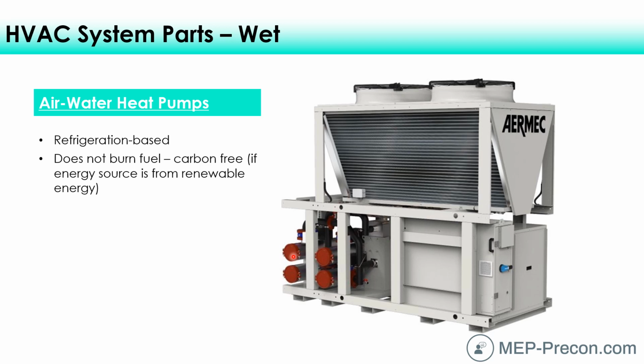So that's a pretty efficient way to get heating hot water, as long as the ambient temperatures are in the proper range. If it gets too cold, these don't operate. And that's kind of intuitive, because if the ambient air is pretty cold, there's just not a lot of heat to be able to pull from to pump into your system. If it's warmer out, if it's 50, 60, 70 degrees, by all means, there's plenty of heat, and this works pretty efficiently that way. But usually you don't need a lot of heat if it's 60 or 70 degrees outside.